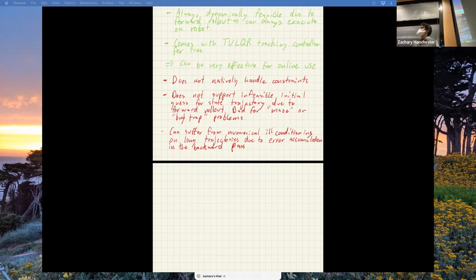Not to be flippant, but it's basically the common motion planning type problems that you would like to solve that it doesn't necessarily handle out of the box, or things involving torque limits, constraints, keep outs, obstacles, safety constraints, that kind of stuff. There are lots of scenarios where this will break. It only handles that pure cost and dynamics setup with appropriate smoothness and all the other conditions we talked about.